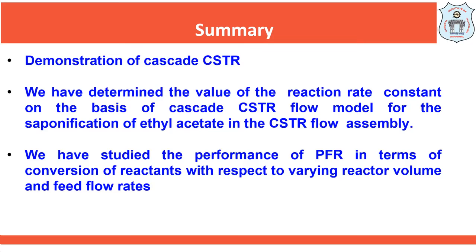In this fourth week of the chemical reaction engineering laboratory, we have demonstrated the Cascade C.S.T.R, where we have performed the experiment and determined the rate constant. We have determined the value of the reaction rate constant on the basis of the Cascade C.S.T.R flow model for the saponification of ethyl acetate in the CSTR flow assembly, and we have studied the performance of the PFR in terms of conversion of reactants with respect to varying the reactor volume and feed flow rates.